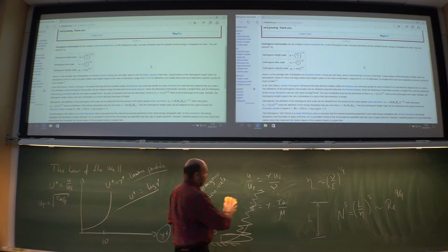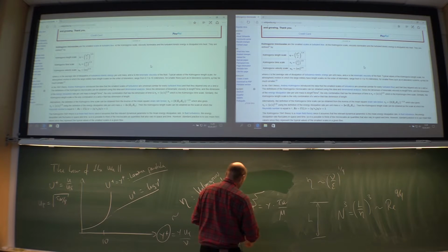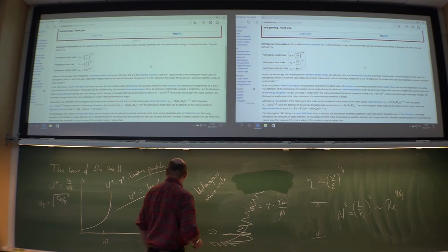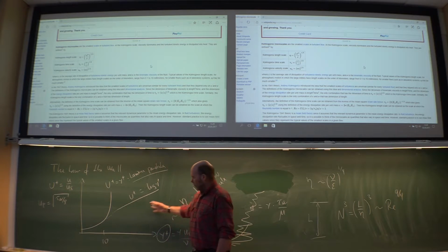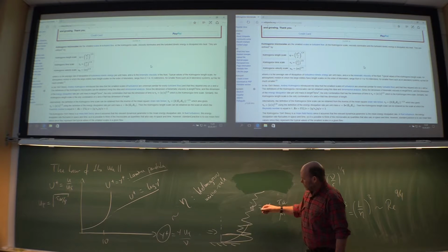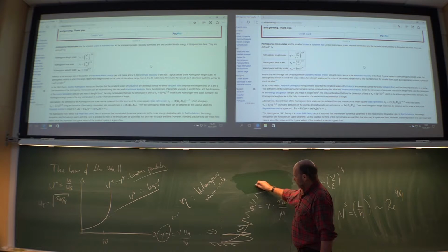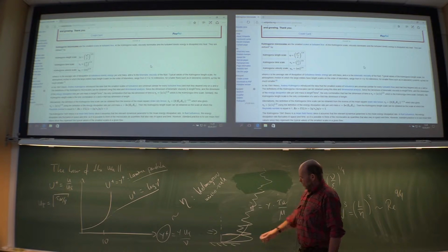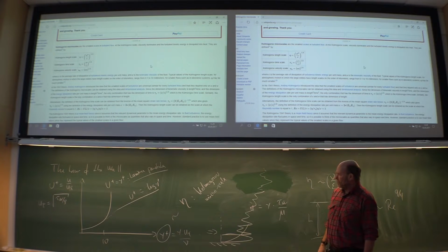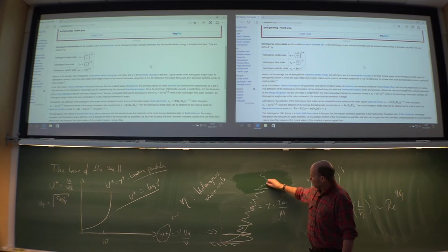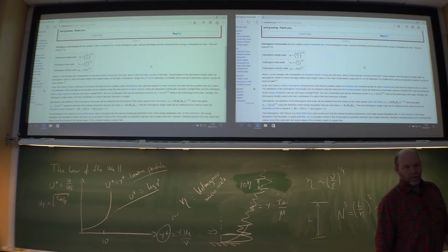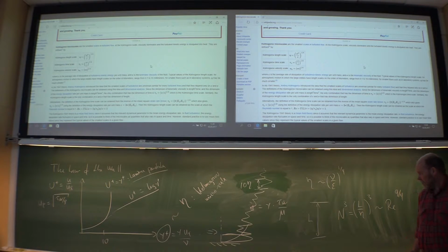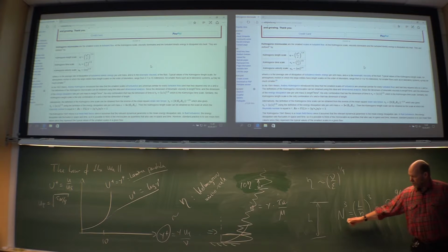And the way we are going to cheat is to say that a little outside of the wall, past the viscous sublayer, in the log area and even beyond, the turbulence is not so intense anymore. It's still turbulent, but not as violent as very close to the walls. Meaning up here, you could have length scales of about 10 Kolmogorovs, and you will still capture the absolute major activity. So yes, okay, we can cheat a little bit here.